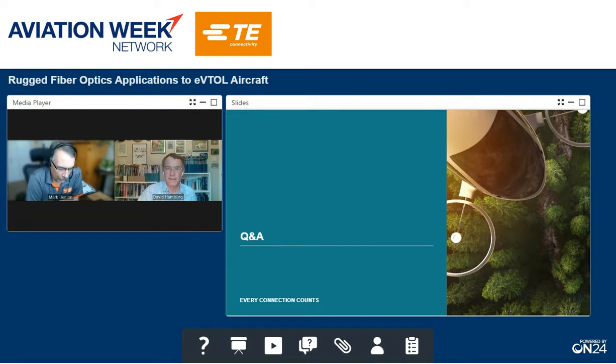Well, there's a couple of things. Obviously, in a traditional mechanical world, you can have your standard vibration detection, monitoring, accelerometers, things like that. But when you look at composite airframe structures, there are Bragg grating-based sensors where the fiber itself becomes the sensor. You can measure temperature, you can measure strain, and that's been demonstrated on aircraft structures and in some applications already.